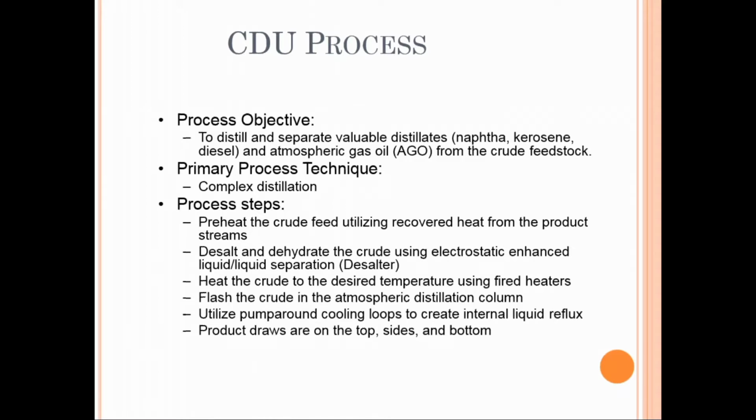All right, back to what we were saying. We desalt and dehydrate the crude oil using electrostatic enhanced liquid-liquid separation. That equipment, the liquid-liquid separator, is what we call the desalter. Then we heat the crude to the desired temperature using a fired heater.